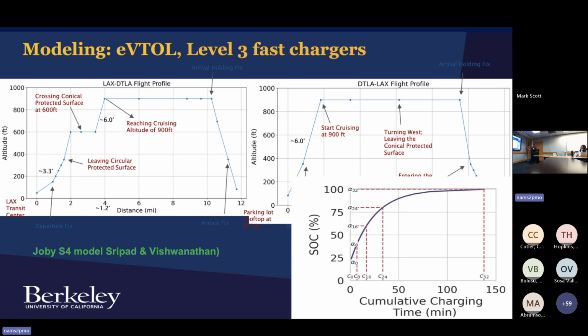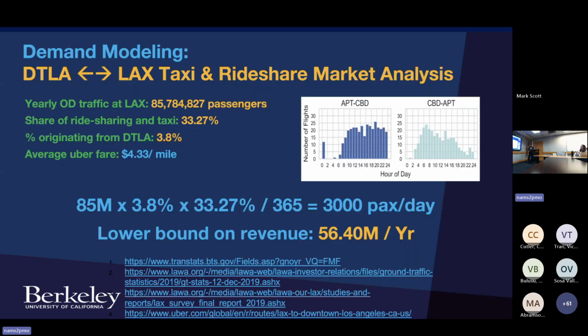So all that varies. The other thing that we do model is the nonlinearity of charging, right? So what you ideally want to do is keep your aircraft operating in this point of charging. So the optimization method considers these nonlinear models and therefore does not push things here. And this you can do if your flight distances are short, right? If you have to fly long flight distances, then you do have to go in there and things become a problem. But in some of the networks I've studied, that happens. In the results I'm presenting today, you're able to keep the fleet operating here. Okay, next.